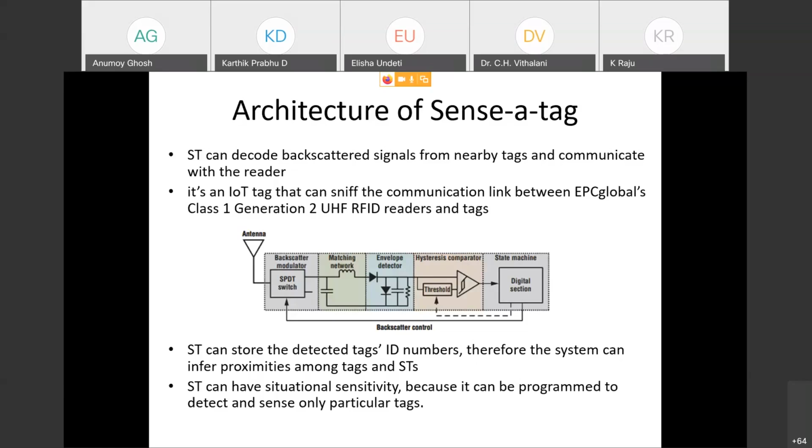Keep this thing in mind, that there will be some range. Say from 2 volt to 5 volt, it will be 0 1. 0 1 means alert. 5 volt to 7 volt, it will be 1 0. 1 0 means brake will be taking over. 7 volt to say 9 volt, it means 1 1 state. 1 1 state means automatic override. Okay, so in this way the state machine is designed, and accordingly the tag will be instructed.